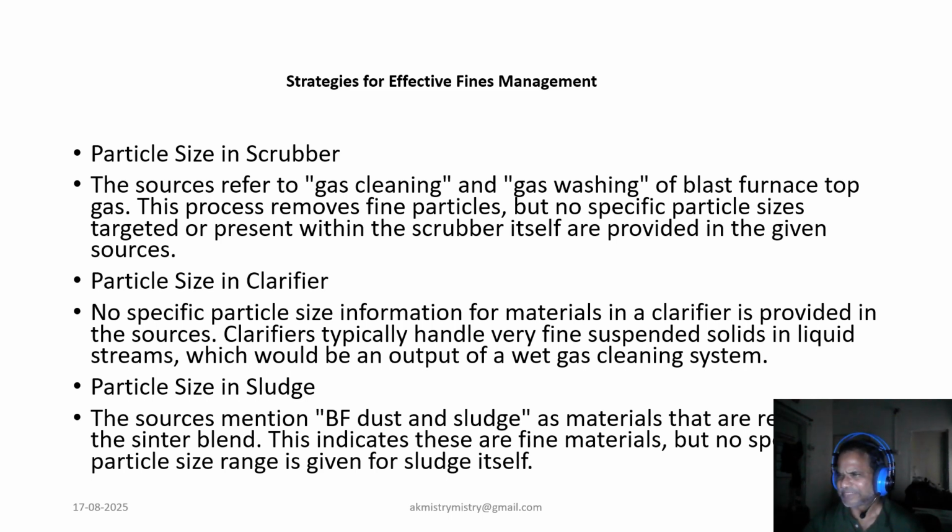Now, given the detrimental impact of fines, what are the strategies for managing them effectively? That is a great question. One key strategy is controlling material moisture. Once we dry out the material, screening out the fines becomes very easy. Dry material is screened much more efficiently than wet material, and wet lump ores, for instance, can carry piggyback fines that adhere to larger particles, making proper screening difficult or even impossible. Reducing moisture content is therefore crucial for effective screening.